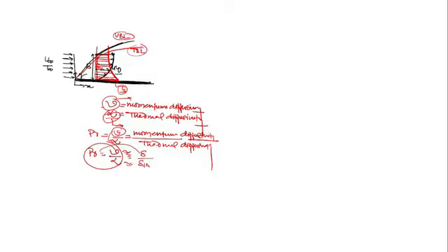So what is the exact relationship? That is, Prandtl number equals delta upon delta th to the power 1 by 3. That I will show you in a later, subsequent lecture. Have you ever studied these terms? 1 by 3. So when the Prandtl number is more than 1, my dear students, then the thickness of the velocity boundary layer is more than the thermal boundary layer.